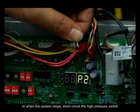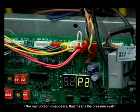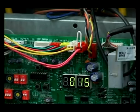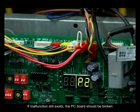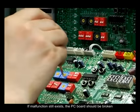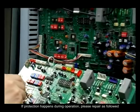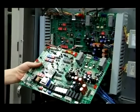Or, when the system stops, short-circuit the low pressure switch. If the malfunction disappears, that means the pressure switch is broken and you should replace it. If malfunction still exists, the PC board should be broken. You have to replace a new one. If protection happens during operation, please repair as followed.